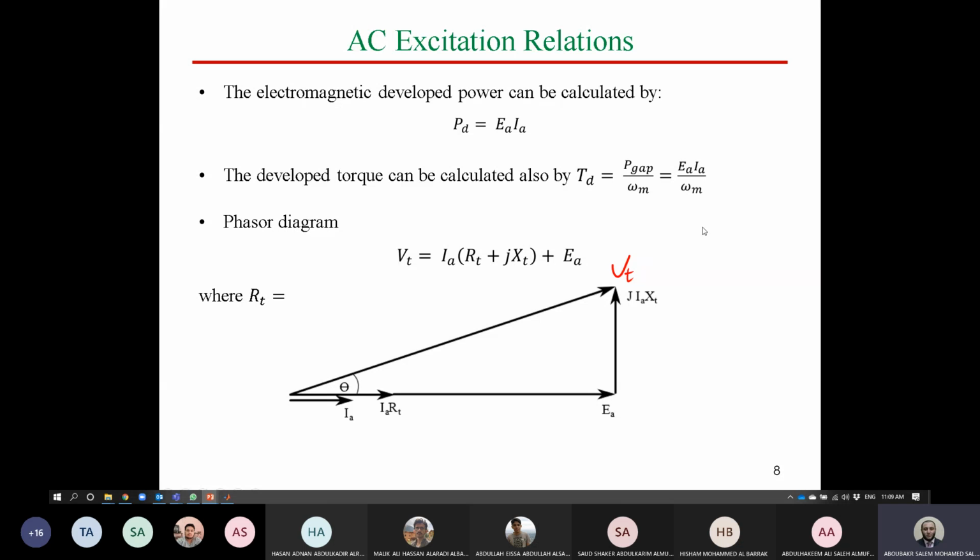Of course, in DC, guys, there is no phasor diagram because DC is DC, it's not vectors, okay, which means everything is in phase. However, in AC there is a phase shift due to the power factor, the current and voltage phase shift, okay, because of the inductance effect of the motor. So this is the phasor diagram of the single phase or universal motor in AC excitation.